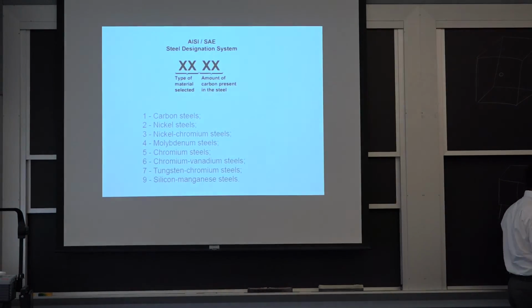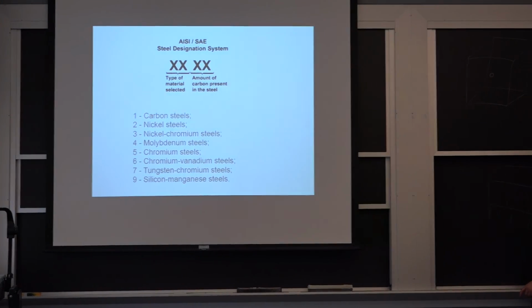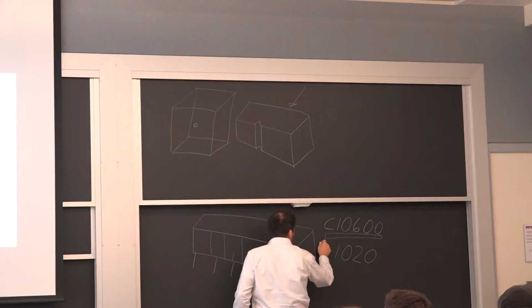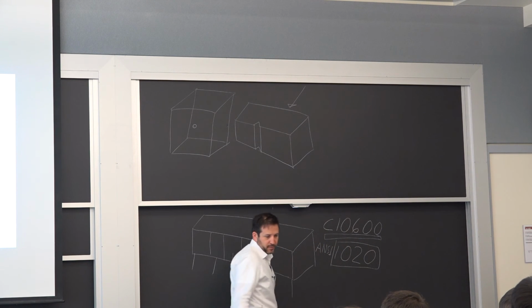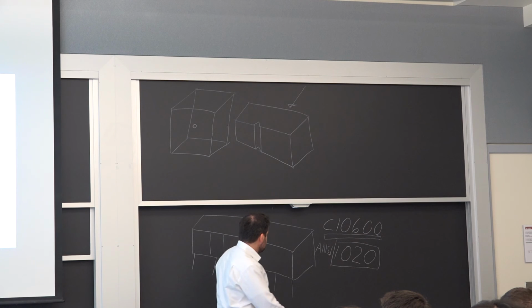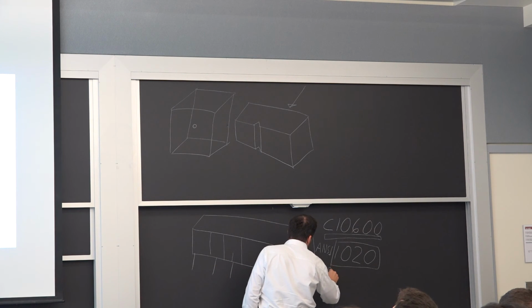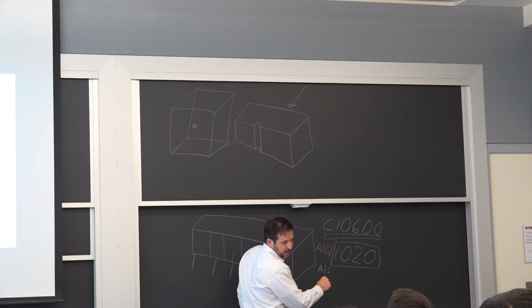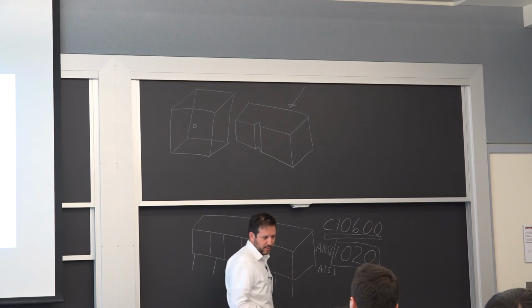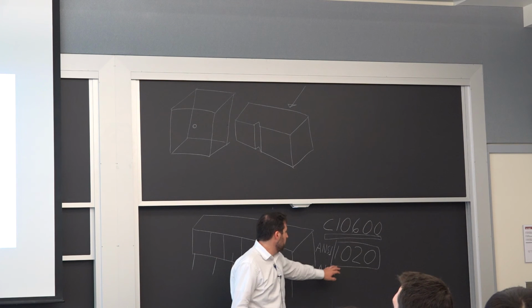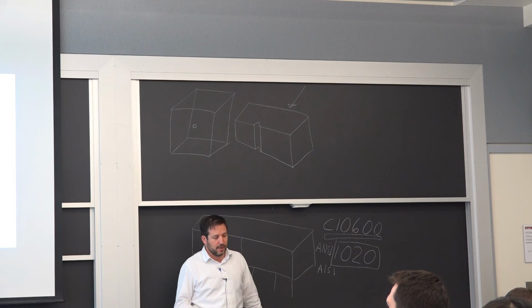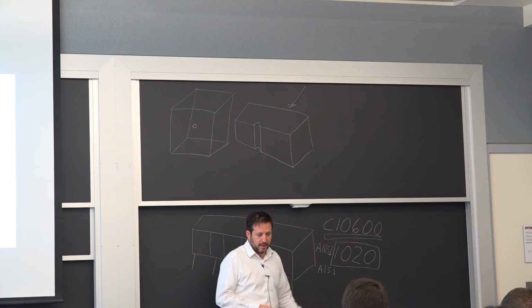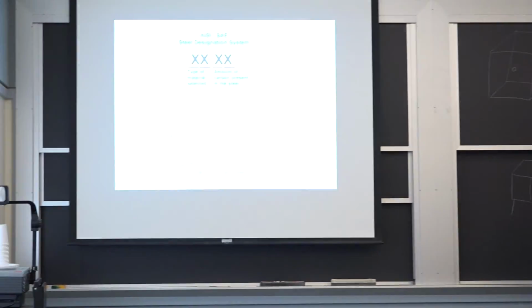Same story with steel. So we're going to try to go through that quickly. A very common type of steel for general fabrication is an AISI steel that will just be a 4-digit number. AISI, the American Iron and Steel Institute. It's the same story where this only tells you the chemical composition. Now, for a certain chemical composition, like 1020, the microstructure could look so much different.